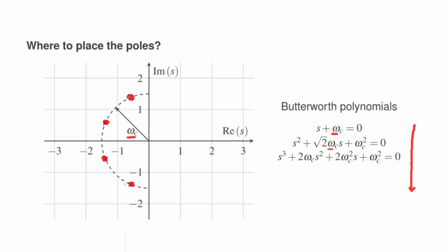The key point to observe about these polynomials is that we may push them further and further into the left half plane by simply increasing the value of omega c. We're going to use this by designing a state feedback compensator K so that the denominator of the closed loop transfer functions of our system are equal to a Butterworth polynomial of the appropriate order. This means that the location of the closed loop poles will be given by the zero locations of the corresponding Butterworth polynomial. And therefore, by increasing omega c, these pole locations can be pushed further and further into the left half plane.